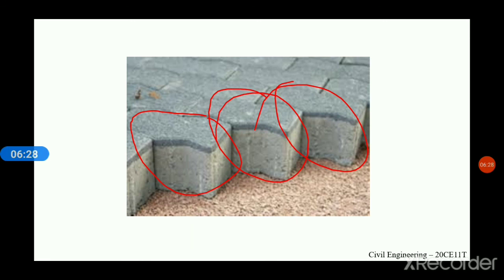So we discussed concrete blocks, solid blocks and hollow blocks. That is precast blocks. As I told you, precast means giving a particular shape and allowing it to become solid before being used. After becoming solid, the block is removed from the mold and kept for curing for a minimum of 28 days. It is the same for both hollow and solid concrete blocks.